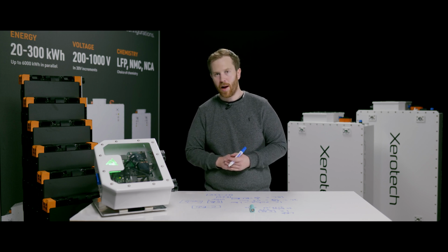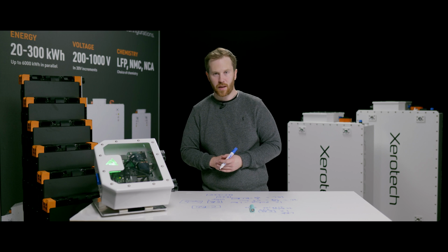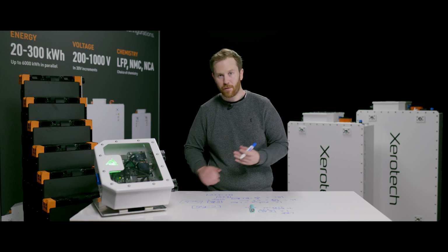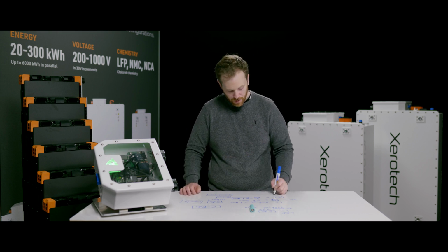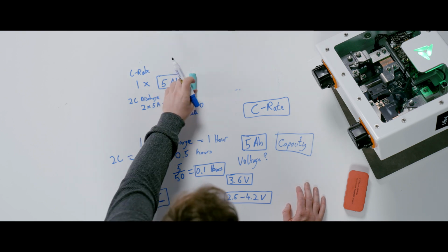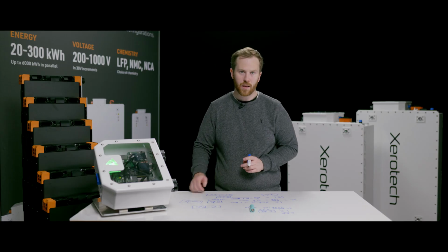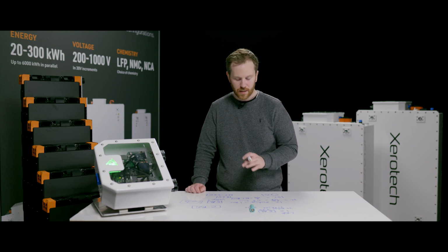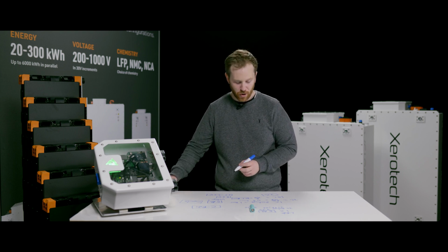When we talk about batteries that are fast charging and can charge in 30 minutes, that means it's charging at 2C, a 2C charge rate, which is very aggressive for many different reasons. The reason these C rates matter, and we need to go back to the equations we used at the beginning, is the equation of I squared R.